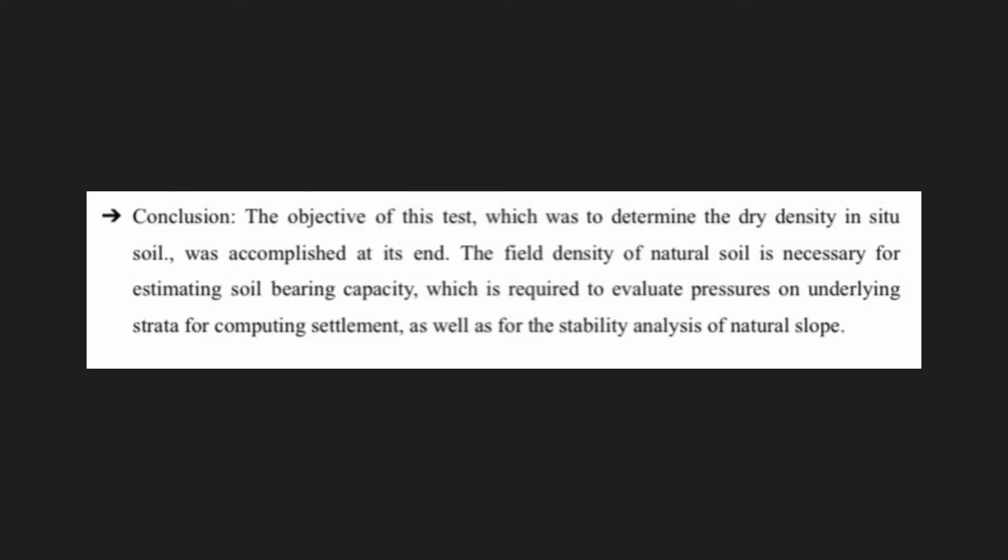The conclusion of this experiment is the objective of this test, which was to determine the dry density of in situ soil, was accomplished at its end. The field density of natural soil is necessary for estimating soil bearing capacity, which is required to evaluate pressures on underlying strata for computing settlement, as well as for the stability analysis of natural slopes.